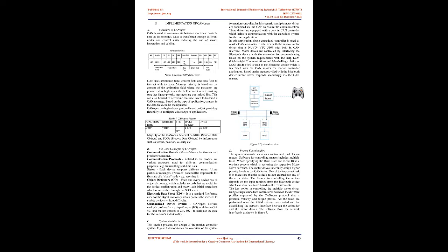configuration capabilities developed for motion-oriented applications. Currently it is used in several domains, such as medical equipment, off-road vehicles, maritime or railway applications. CANopen protocol consists of 6 core concepts which are discussed in Section 2, one of them is the Object Dictionary. Object Dictionary plays a vital role in this protocol, which acts as a database for the features applicable in communicating with the devices or the application along with the concerned data in the communication.